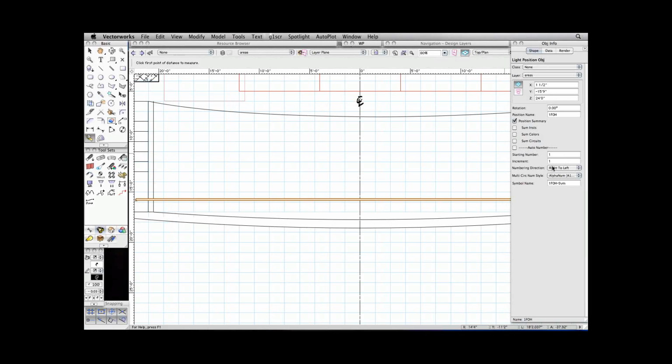Vectorworks is smart enough to know, if this is checked on and we have 5 instruments across and put an additional instrument between instruments number 1 and 2, that it will automatically renumber: the added instrument is number 2, and it renumbers all the rest of the instruments on that position. So in early days of the plot, I'm actually leaving that checked on.